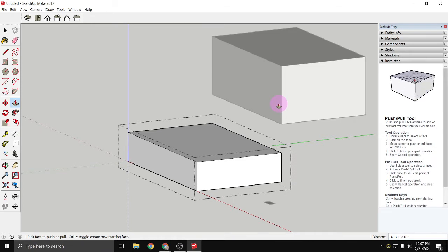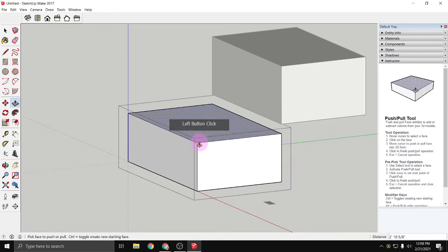And so I always recommend students group things as they go to just kind of make their work a little bit easier, because I can still edit things, but chances of me somehow getting rid of three-dimensional objects and just making random 2D faces that kind of collapse in on each other, or maybe accidentally deleting edges that I don't even realize I deleted, chances of that happening are a lot less if we are using components in groups as we work.